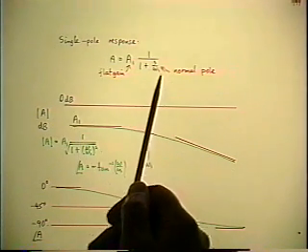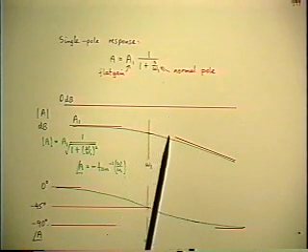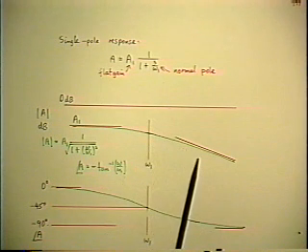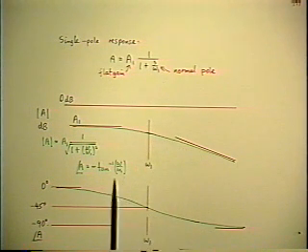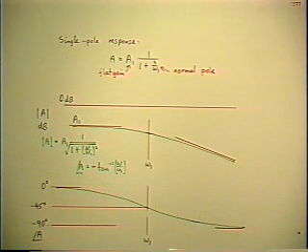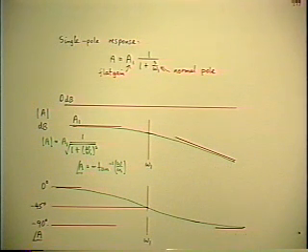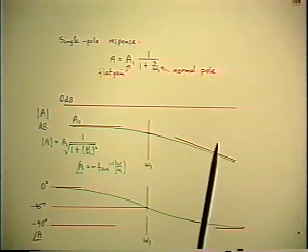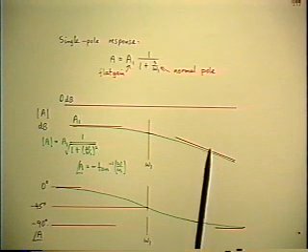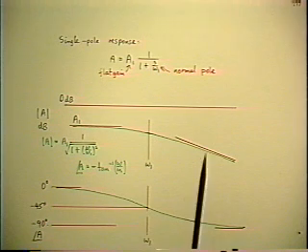Then you jump to infinite frequency and see what the magnitude does, and it goes as 1 over s, or 1 over j omega, which is a reciprocal function. Since we've chosen double log scales, a reciprocal function is also a straight line, which is the red asymptote shown up at the top end. And that line has a slope of 20 dB per decade of frequency, which is just a complicated way of saying 1 for 1, or 10 for 10, because it's a simple reciprocal.